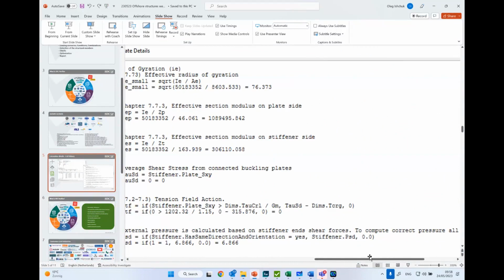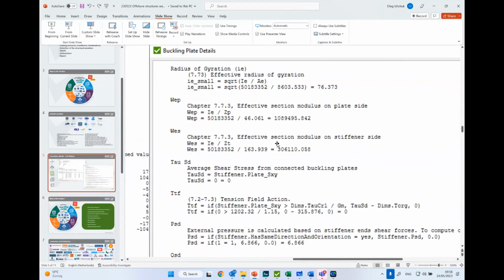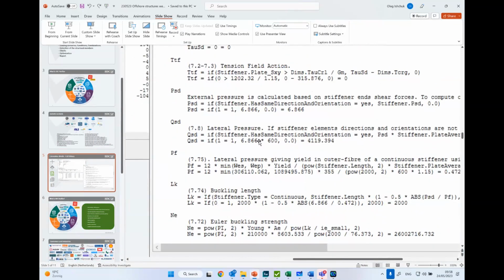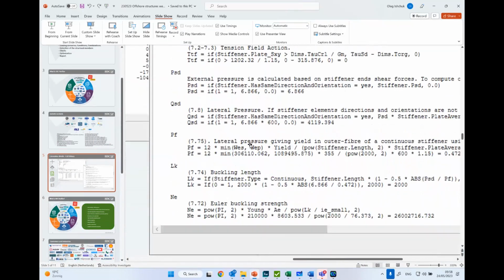So basically like a hand calculation, you can show every formula, intermediate result and intermediate values for a specific member or element, and include that in the report. Yes, it is possible, and it will look like this. You can also export it to a text file or some kind of editor for yourself. Thanks for the question. This is a good one.